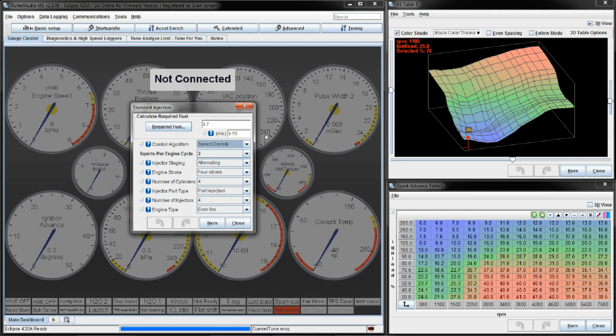Anyway, so you're looking at the speed density here. This is pretty much the way this car was factory, speed density. So you'll know the difference between speed density and MAF, because a MAF, like a lot of the cars starting with the LT1 Camaros and stuff like that, I don't know who started it, I think probably the import cars, they actually have different types of airflow meters to get the amount of air right from the air flowing by. So there'll be a hot wire that it cools down, or just various other methods. I think there's about 3 different types out there, but we're not using that because I didn't want to rig up a MAF, and speed density is fine. A lot of people use it.